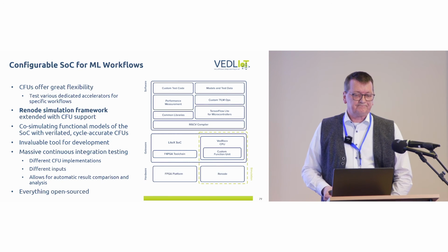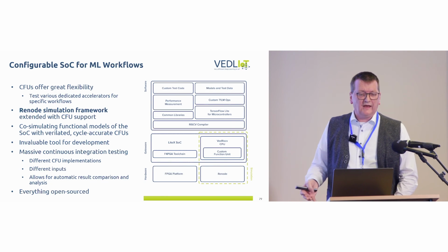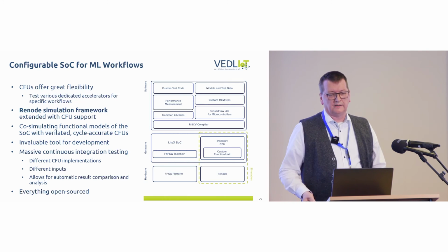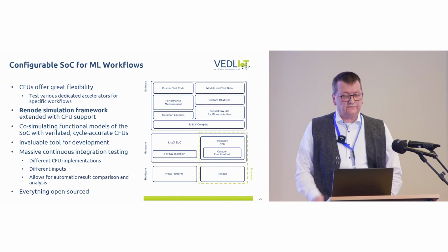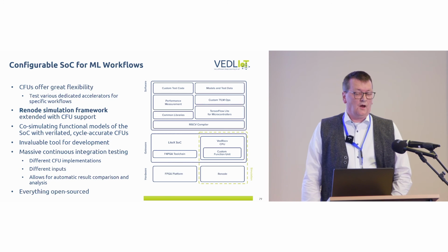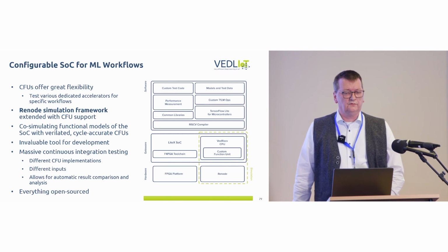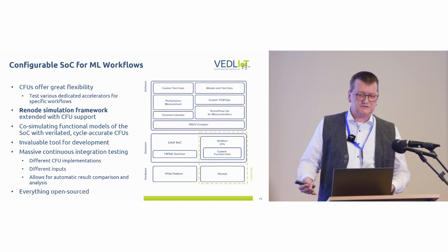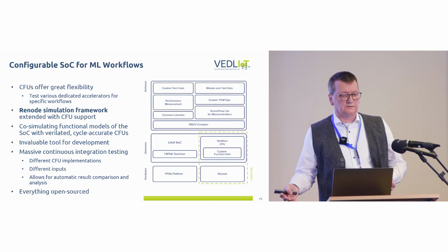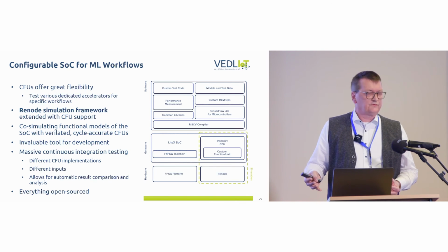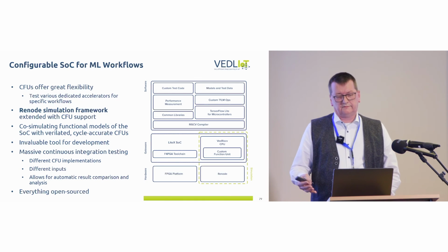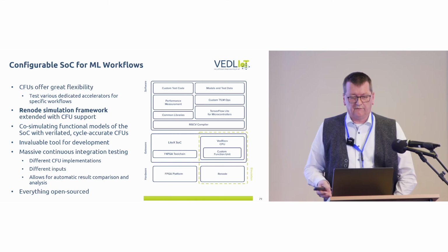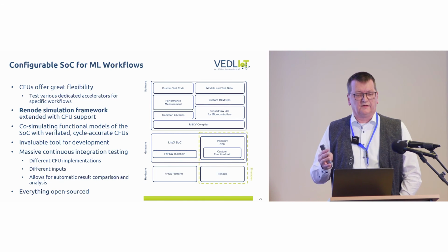Renode can be used as the simulation framework already presented by Pedro in the beginning, and it has been extended with support for custom function units. So you can do the co-simulation of, for example, the functional model of your CPU, of the complete SoC, with cycle-accurate, for example, Verilator-simulated custom function units.